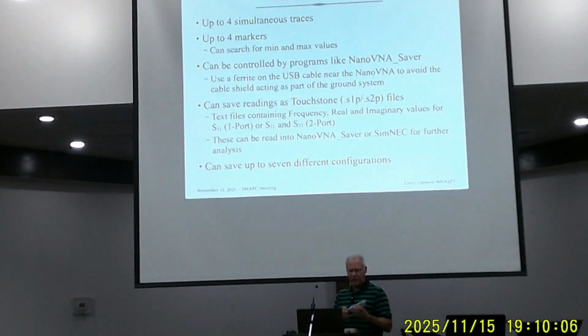This one, depending, there's different ones, but you hold certain buttons or knobs and turn it on, this becomes a USB drive. So it looks just like a flash drive plugged into here. If you plug this into your computer, a disk will show up, and that's where those Touchstone files are stored. So you just take those and drag them over to your computer. You can open those like with NanoVNA Saver, and you can see all of that stuff on your computer now to do different work with it and look at it more.